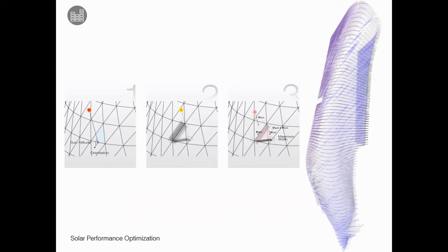To do that, I put an agent on each panel, and they search for the best performing angle, or orientation. In this case, the agent searches the solar location through the year, finds the altitude or azimuth of the highest sun through the year, and then we adjust the angle based on that. Actually, the location is fixed, and only the angle changes. In this case, the agents don't really interact with each other, so it doesn't need to be agent based.